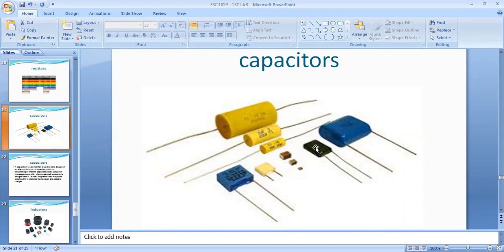Sometimes our fan is not running, not revolving. Your electrician comes and tells you that the capacitor is very old, please change the capacitor. When you go to the market, the store owner gives you a 2.25 microfarad capacitor. When you replace the old capacitor with the new one, the fan speed is just like new, right? The ceiling fan capacitor rating is 2.25 microfarad.